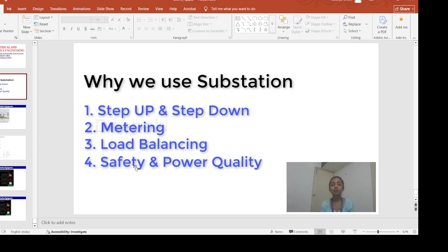So how can that power factor be improved? We need to use shunt capacitor banks in the transmission lines. They are usually located in the substations that are near the load. It will improve the power factor of the transmission line.